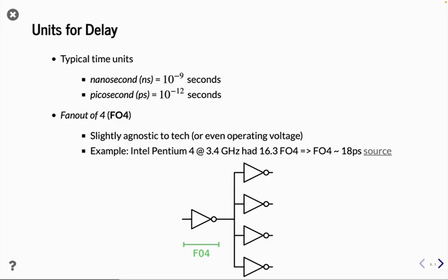The same circuit manufactured in a smaller and smaller process tends to go faster, right? That's one of the things we hope for from Moore's law. And so a design from 20 years ago has a certain latency, or a certain delay. The design from today has a certain delay. And you might say, oh my gosh, based on delays, the one from today looks a lot lower. But the question is, is that due to the design or is that due to the process? Well, the changes in process are so dramatic that usually it's due to process.